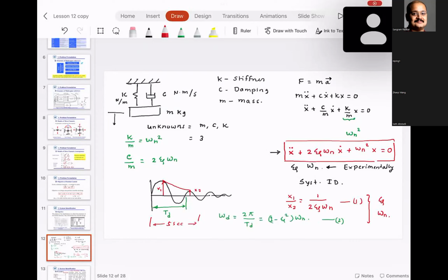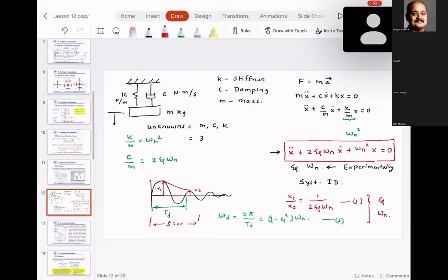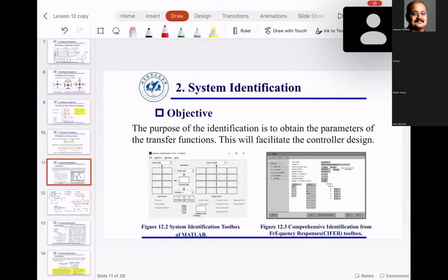The same thing can be done for system identification, wherein you capture this experimental data, and you feed that data to either software or some type of mathematical algorithm. There are a lot of mathematical algorithms that would do system identification. You can do dynamic decomposition, you can do mode analysis, or you can use MATLAB, you can do the system ID in state space, transfer functions, and so on. And finally, you get this system model.